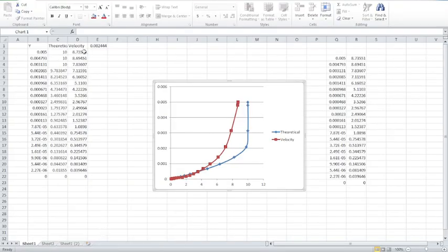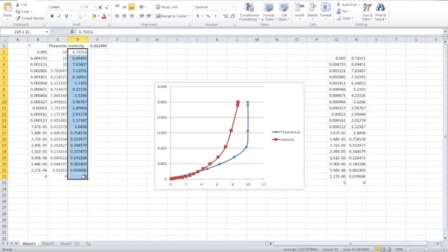So what I've done here is calculated, this is the velocity that they've given me from Fluent. This is the velocity that I've calculated using this equation right here. This is our y. And you can see our theoretical seems to increase in speed a little quicker and reach that free stream velocity, which is what we predicted with our boundary layer being lower than it shows in those graphics.